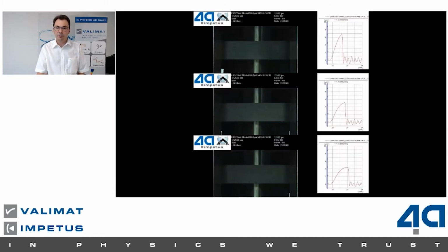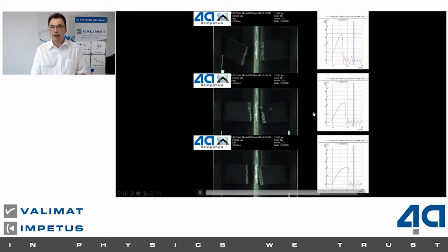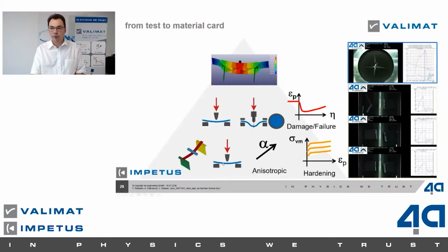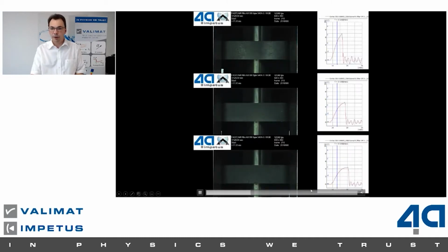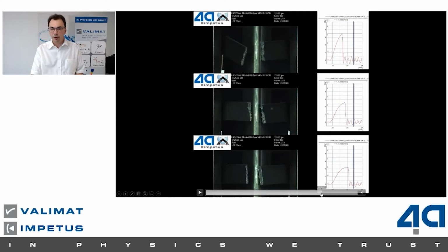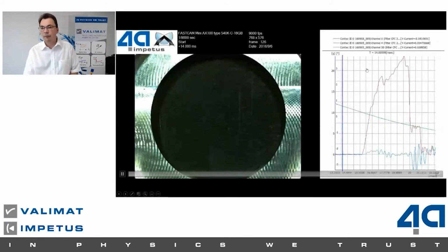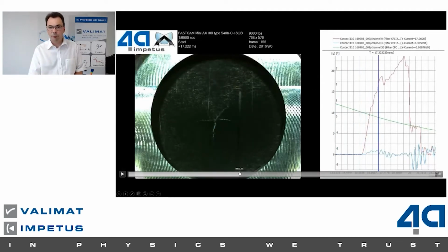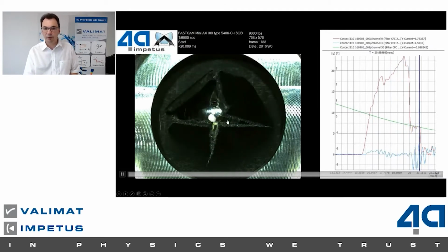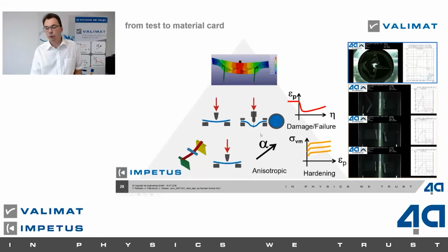So in that case, we typically would start with dynamic bending tests and static bending tests under different directions. So you can see it fails differently. In zero direction, it fails earlier. And if you look at the transversal direction, I go back here, you see we have first some wrinkles in here, and after the matrix is failing locally, then the whole composite is failing. And you see this also in the signals. On the other side, if we do a puncture test, we can see quite well what Stefan was also showing. We have an initial crack, and after this initial crack, the crack is propagating, and that's something we like to consider in our material modeling to be predictive in our simulation.